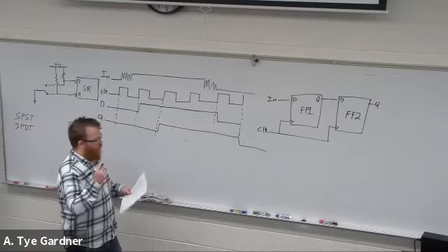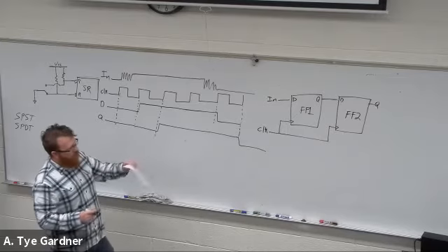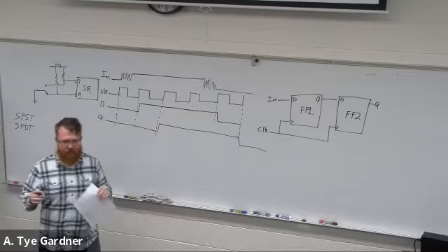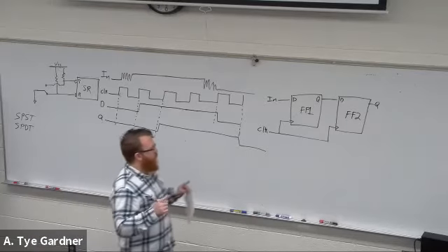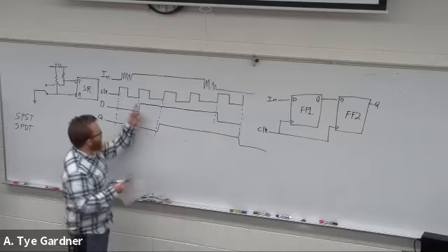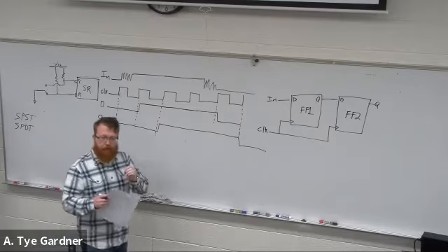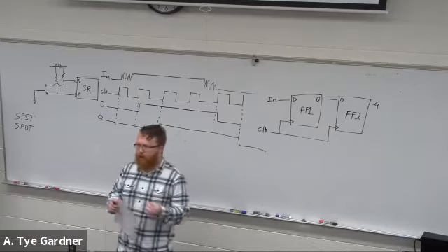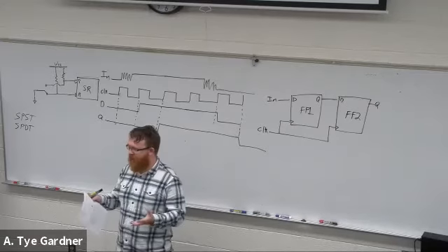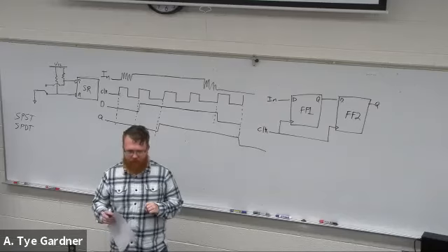there is one more concern, one more issue that we have left to deal with. In this case, we still need the slow clock. Not really that big of an issue in an FPGA, we have tons and tons of logic. But the next thing we want is for it to be truly synchronized to the system, which it is. It's doing a decent job of synchronizing here. But I've talked about, especially in high-speed systems, like your ready signal, where you want it asserted for 1 clock cycle. You just want it to flick on and flick off. That's pretty standard design criteria for a lot of systems that you're going to get. Is ready is going to last for 1 clock cycle.